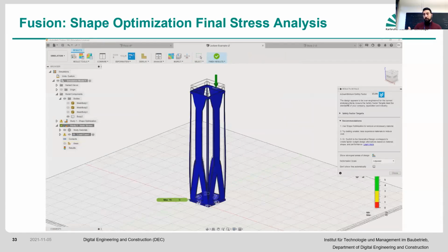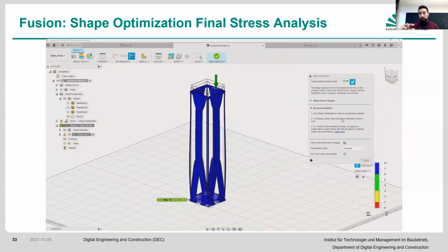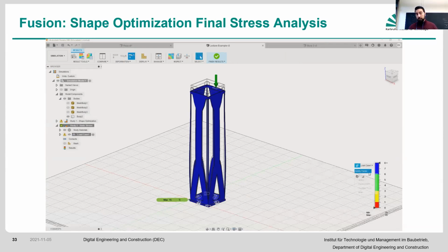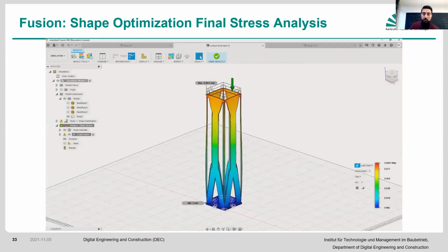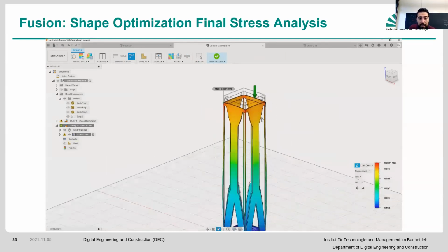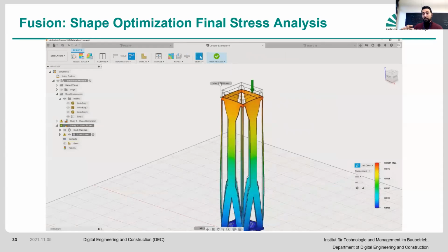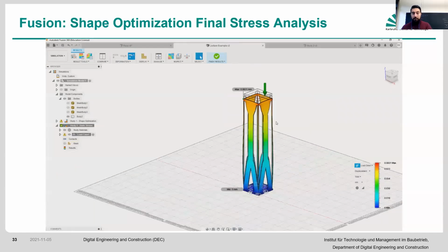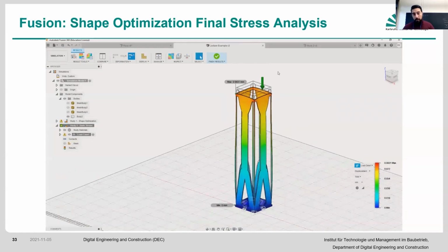That means that if the Young's modulus is larger, the amount of displacement is going to be smaller, right? If it's smaller, then the displacement is going to be larger. For steel, the Young's modulus is quite high, so the displacement is going to be much smaller. Here, for steel, you have 0.8 millimeters. That means it's very, very little. Of course, this is very exaggerated, right? It's not actually displacing this much. This is 0.8 millimeters at the maximum. So that is for steel.